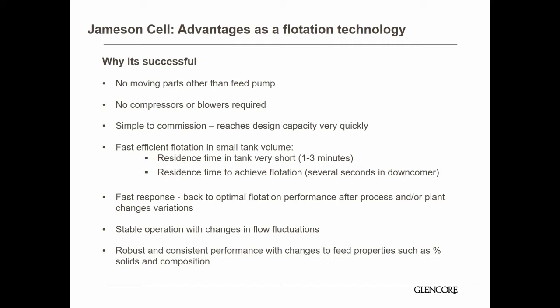The cell offers a robust and consistent performance over a wide range of operational variables, and the performance of the recleaner Jameson cell allows feedback to the performance of your grinding or regrinding circuit. Did you do a good enough job to get high enough liberation to get high grade? And it's great that your flotation circuit can easily tell you that.